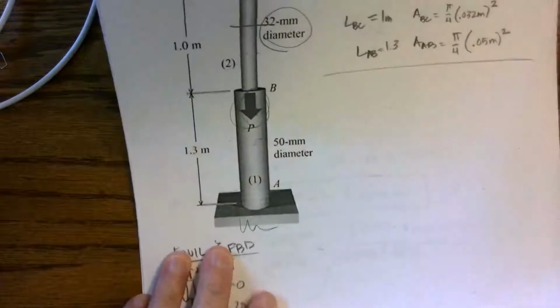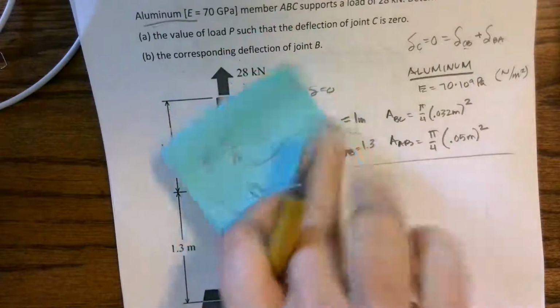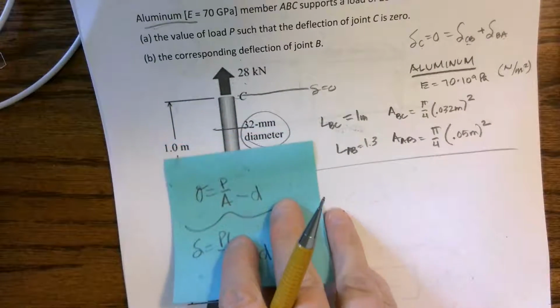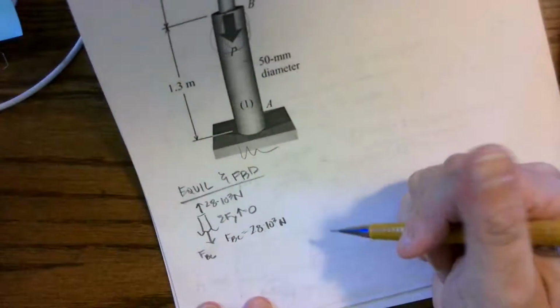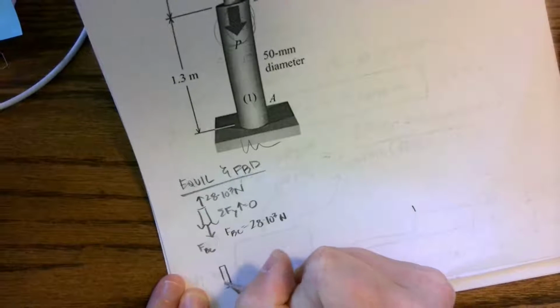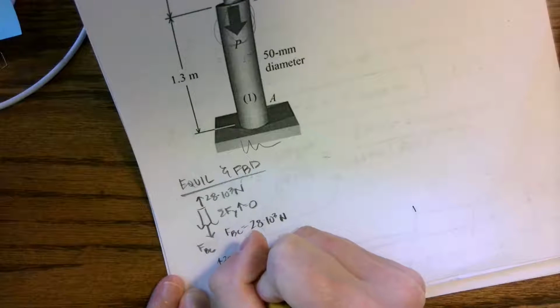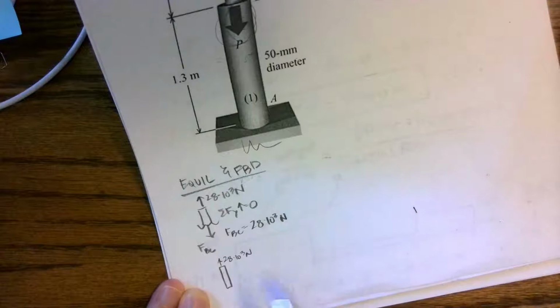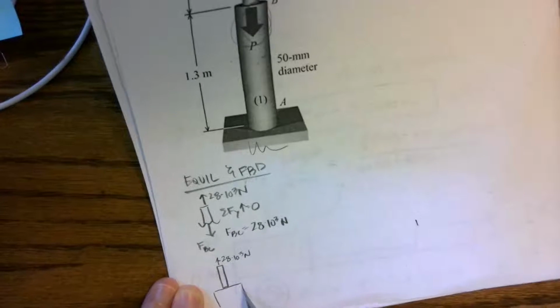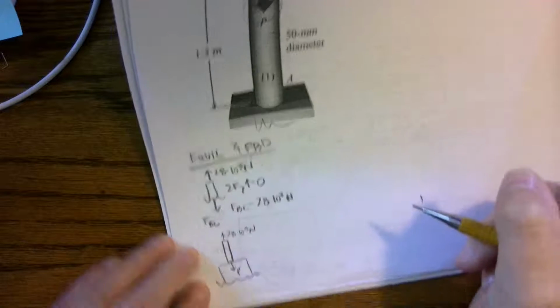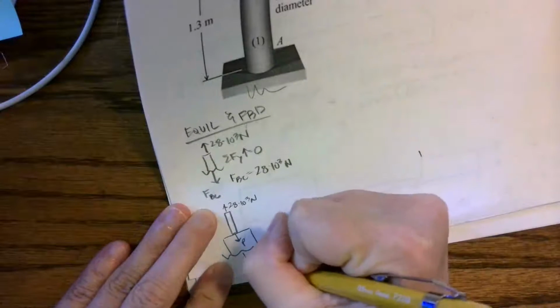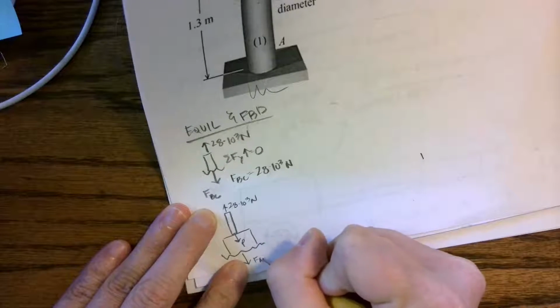Now I'm going to go back to our picture here, and I start at the top, so I have to include all of this, all of that. Now we're in B to A. So my free body diagram has to look like this, with everything that was above. Here's the top part. It is being loaded with 28 times 10 to the 3rd newtons. And then I have part of the bottom part. It doesn't matter, I'm just cutting it somewhere in there. I have this force P that I don't have the value of. And we assume everything in tension, so I have the force of AB.